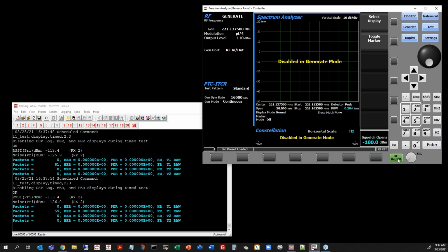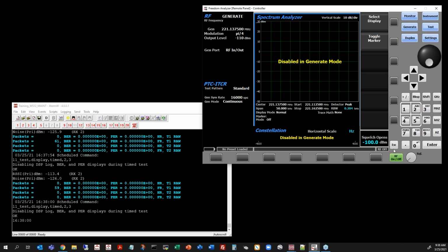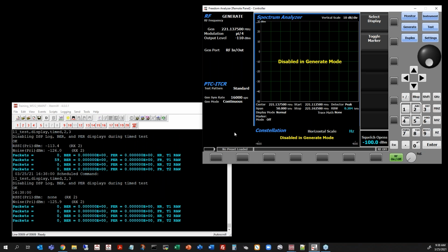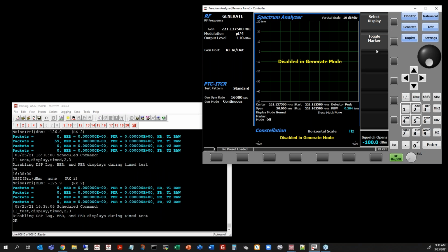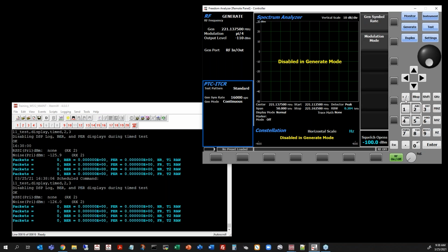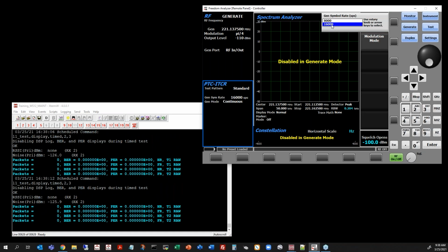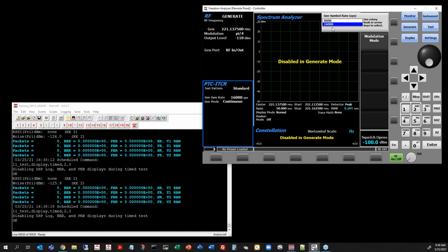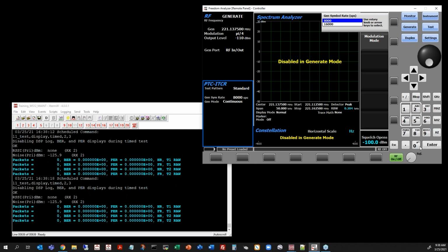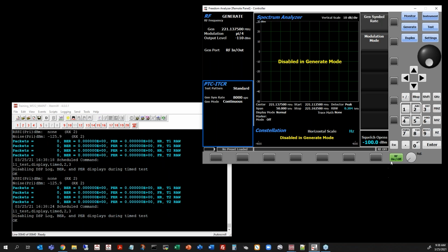So let's go ahead and change that. The output level will be to press the number 1. He's just going to switch to the half rate, so he needs number 4. Okay, number 4, that's what I'm looking for right there. And here's our symbol rates up here. I was doing full rate, which is 16 kilosymbols per second, and then I'm going to move it to 8. I'm going to hit the enter key, and I will turn my generator back on again.